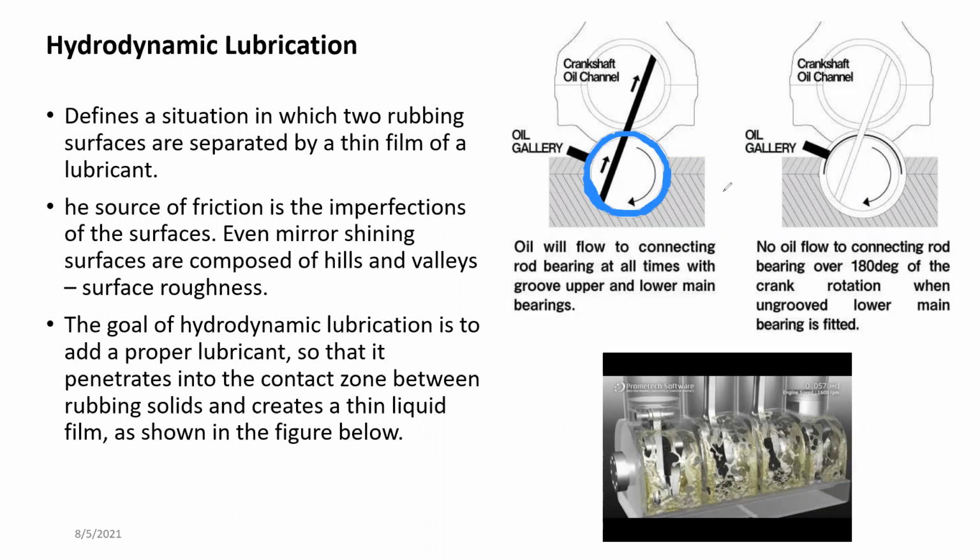This hydrodynamic lubrication system can take a lot of load, as long as you can increase the pressure of the lubrication system and maintain these gaps exactly correctly. These gaps need to be very well measured and machined in order to work perfectly. That's one of the difficulties in these lubrication systems.